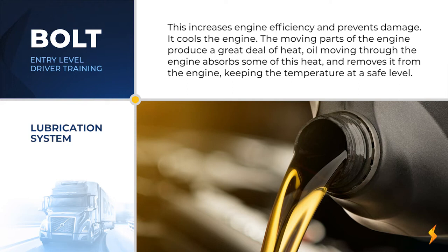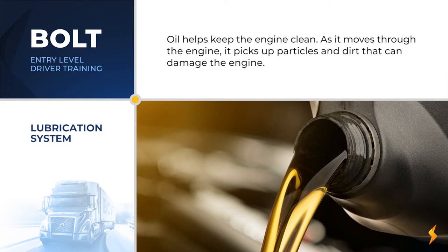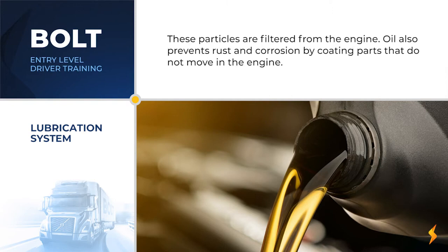It cools the engine. The moving parts of the engine create a great deal of heat. Oil flowing through the engine absorbs some of this heat and removes it from the engine, keeping the engine temperature at a safe level. It cleans the engine. Oil helps keep the engine clean. As it travels through the engine, it picks up dirt and other particles that can damage the engine. These particles are filtered out of the engine. Oil also prevents rust and corrosion by coating surfaces that do not move within the engine.